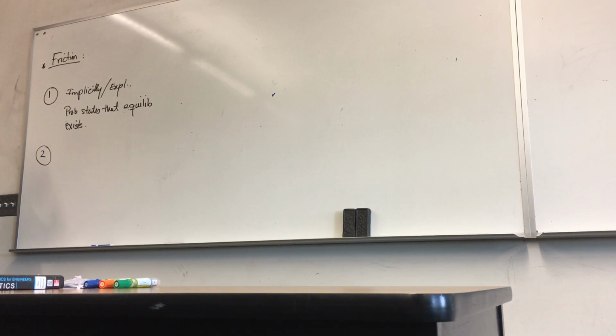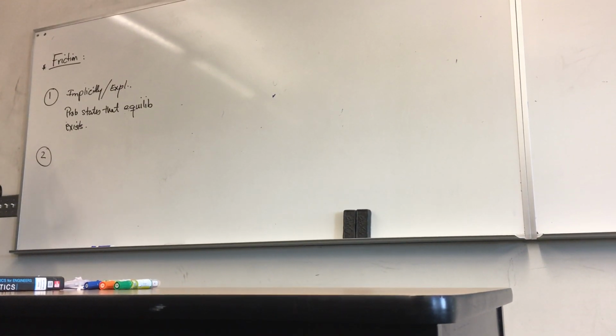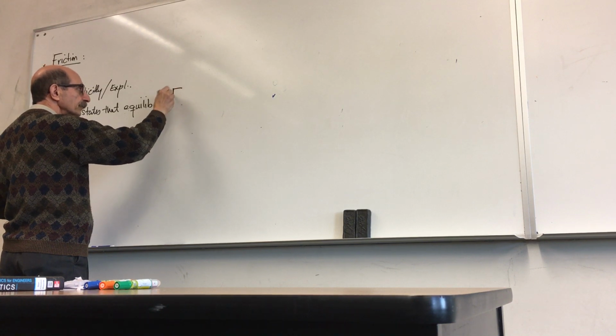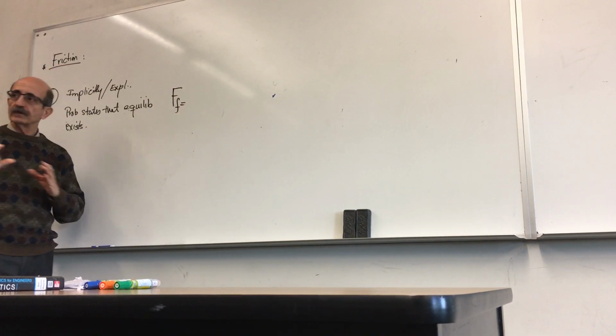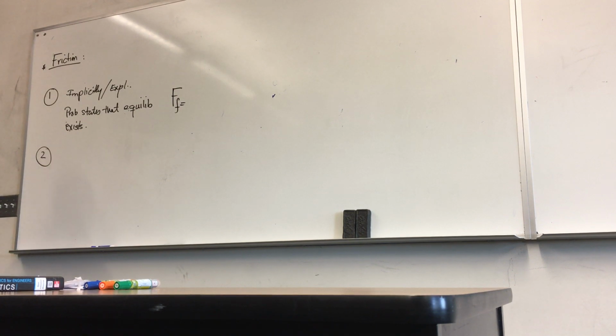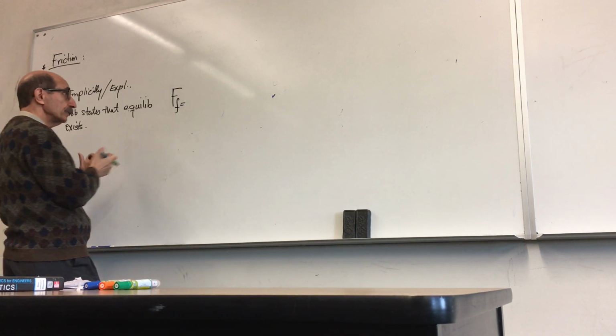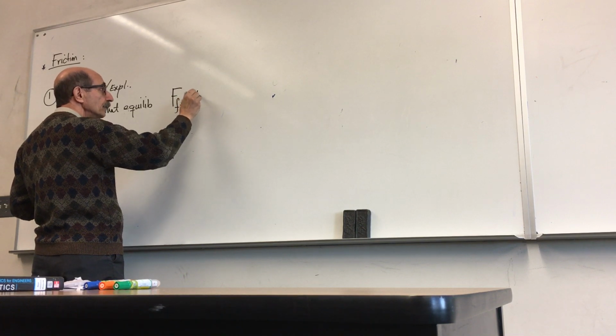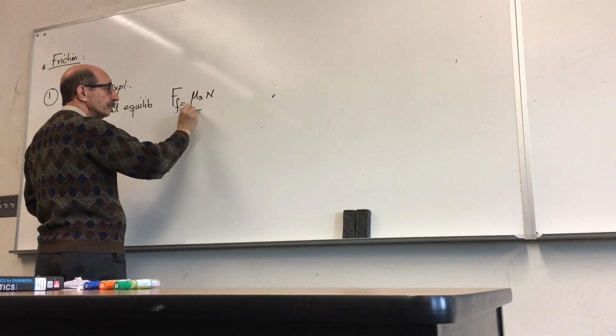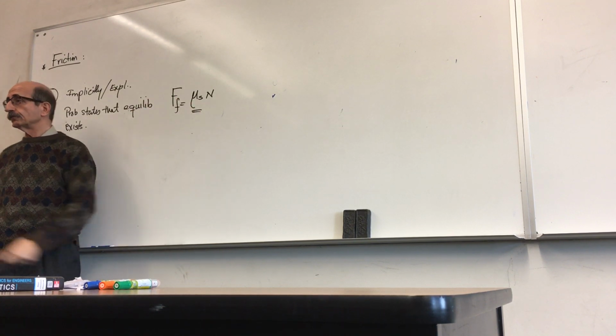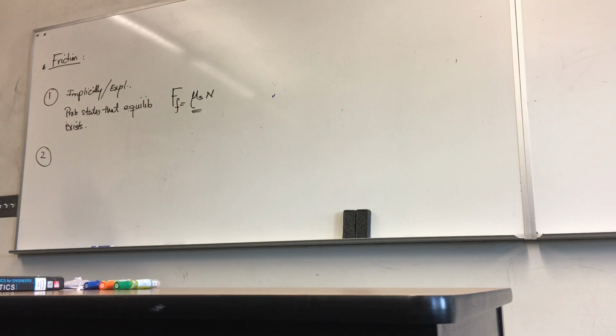That for whatever way it is stated, it directly or clearly implies that no motion is going to take place, and this structure, piece, whatever, is in equilibrium. That means the force of friction that develops at that point of contact, or the potential slippage between the two pieces, is going to be a maximum that is mu s, coefficient of static friction, times the normal load that develops perpendicular to the potential direction of motion. Okay, so that's case number one.